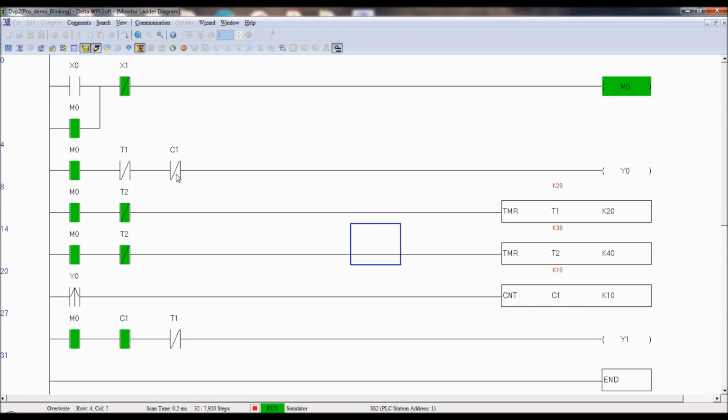So now it is L2, so L2 is going on, off repeatedly, but we are not counting the Y1, not counting the L2, right? So again we have to use a second counter. So up to here it is fine.